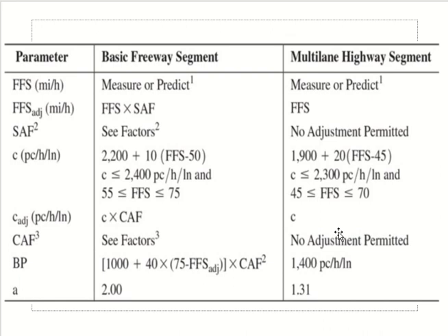Okay. Now you calculate the break point. So they are saying use adjusted free flow speed, and then they are saying put capacity adjustment factor as well. Any data about adjustment here? Weather, incident, work zone, driver population. Driver population is mentioned, but it is mentioned as all drivers are familiar. Familiar means no adjustment. Familiar is a standard.